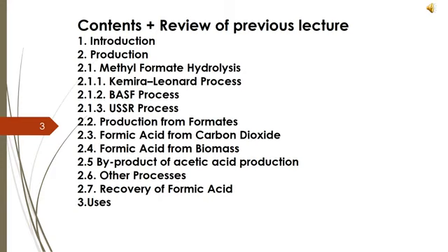Now what happens in F? In this acid separation column, the contact time is minimized by the internals. With a small liquid hold up, the distillate is separated into methyl formate and methanol in the recycle column. Now we have done the distillation in the acid separation column, and then we have separated the distillate in the recycle column F. So F is the recycle column.